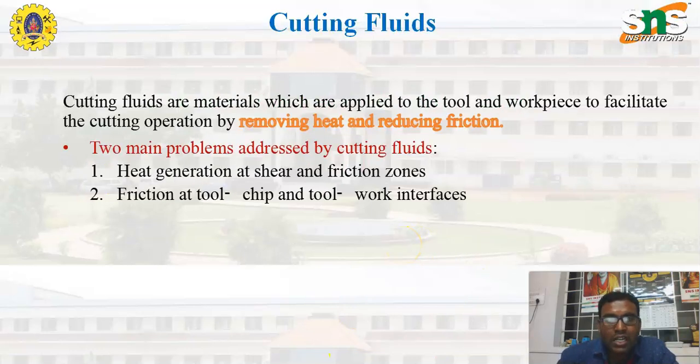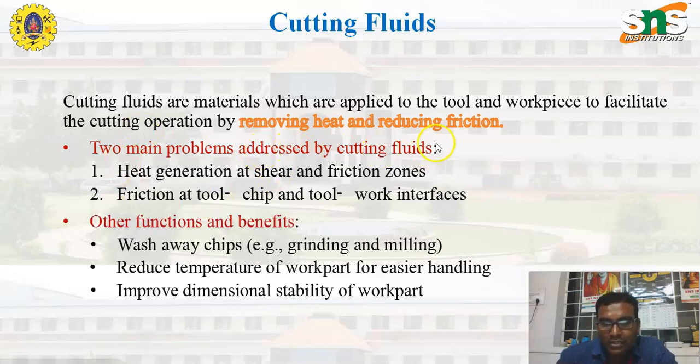What is cutting fluid? Cutting fluids are materials which are applied to the tool and workpiece to facilitate the cutting operation by removing heat and reducing friction. The other name for cutting fluids is coolant. The coolant is used during the machining process in order to reduce the heat and friction. The two main problems addressed by cutting fluids are friction at the shear and friction zones, and friction at the tool-chip and tool-work interfaces.